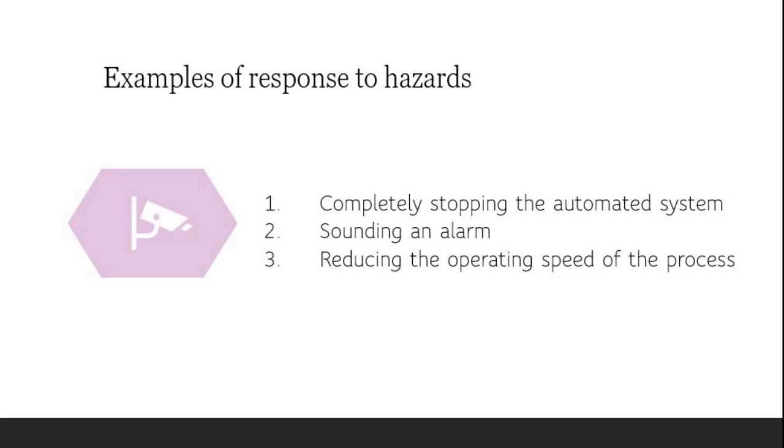Sensors for safety monitoring range from very simple devices to highly sophisticated systems. An example of a very simple device is a limit switch, which detects proper positioning of a part in a work holding device so that the processing cycle can begin. More advanced sensors are pressure sensitive floor pads to detect human intruders in the work cell, or a machine vision system to perform surveillance of the automated system and its surroundings.